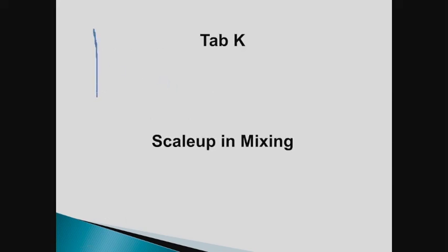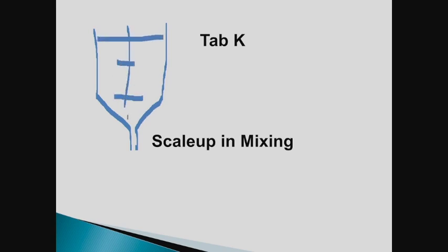One reaction had a tank shaped like this, and the solid-liquid surface up here, and a couple of impellers in there. All the solids were buried here, down in this exit pipe. And they couldn't figure out why the reactor wasn't performing. Catalysts were down here, unavailable for processing. The reaction essentially did not occur.